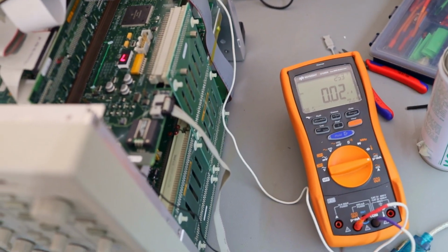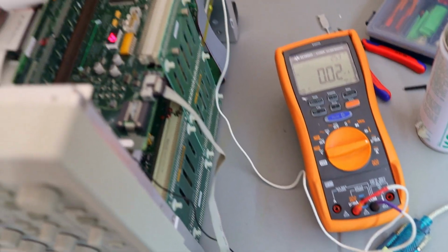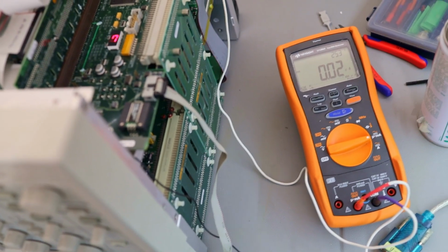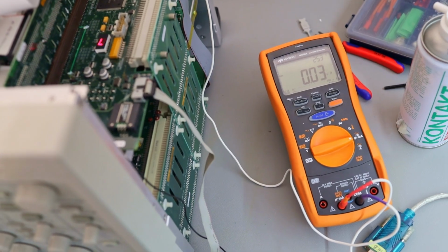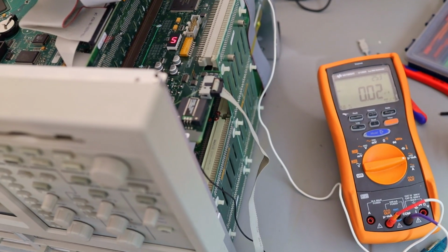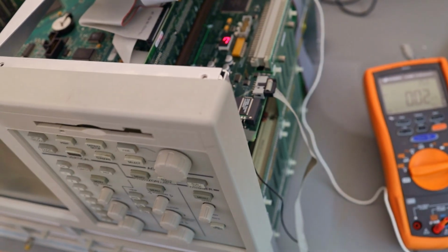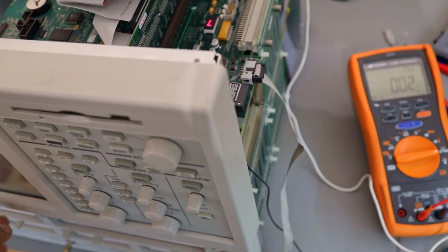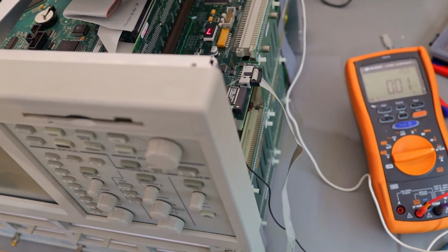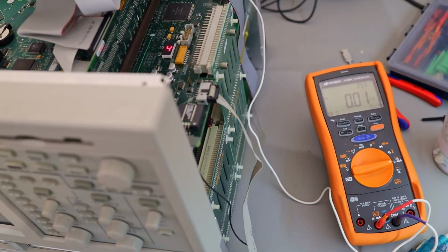So again, to test the power consumption of the NVRAM module, I have hooked my multimeter in series and powered the NVRAM's backup cell from a bench power supply. Right now you can see the instrument is on and it's consuming around 0.02 microamp. I believe it's the residual. As I have told you, these RAMs have a lot of capacity. These RAMs need power, and now I will turn off the instrument and you will see if the power consumption changes when the instrument turns off.